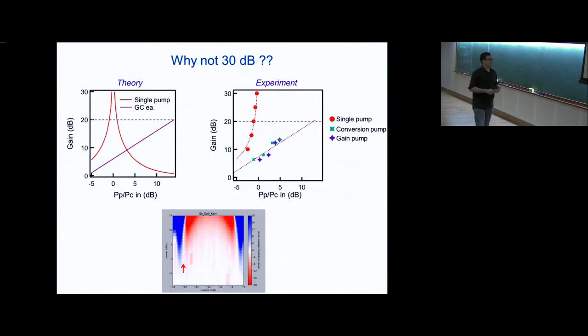If I go back to this idea of fourth order cancellation, you start to get a clue. So here, in a singly pumped amplifier, here's the divergent gain profile. We've just normalized this to be 0. Here's the each pump profile of this quadrature coupling. And experimentally, it really makes sense. But what you see now is that I'm now pumping each pump 10 and 15 dB. So that's 10 or 20 times stronger than the ones before. So my net power in the system is something like 50 times what I used to have.